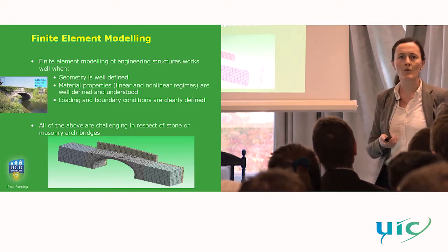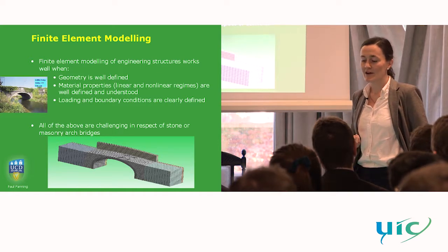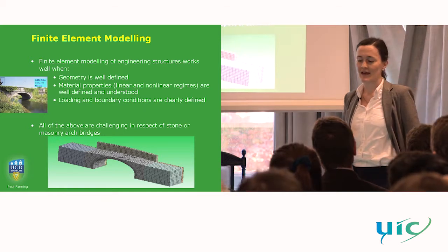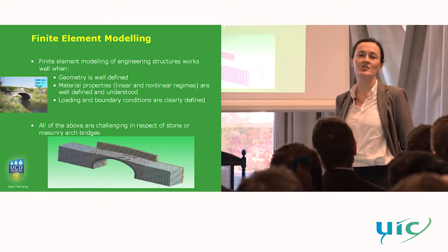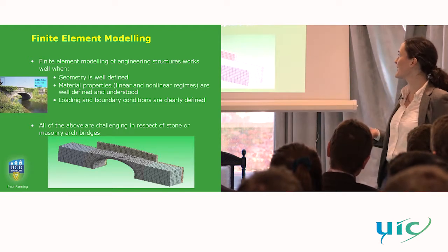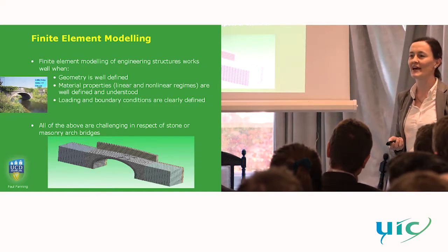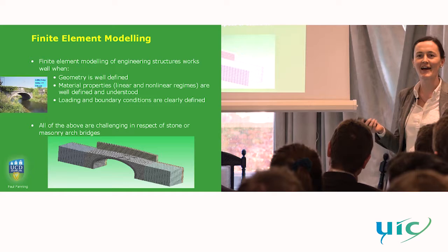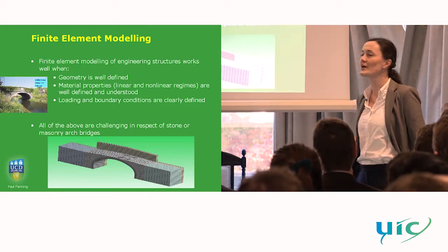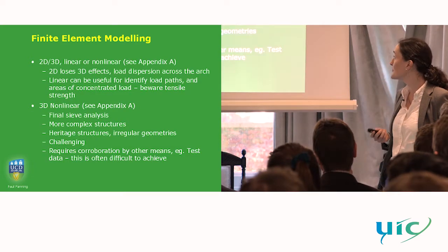Generally, it works quite well when the geometry is very well defined, when your material properties are well known and well understood, and when the loading and boundary conditions are clearly defined. With respect to masonry arch bridges, all of these are particularly challenging. So you come in for quite a lot of criticism modeling masonry arches using an FE approach, and it really does require quite a bit of caution and care.